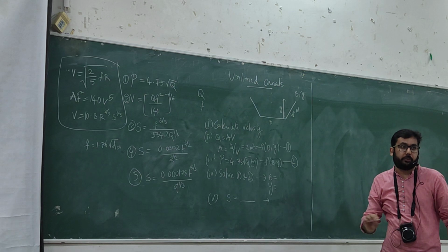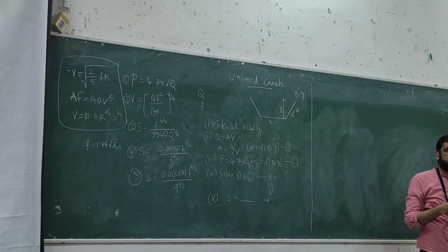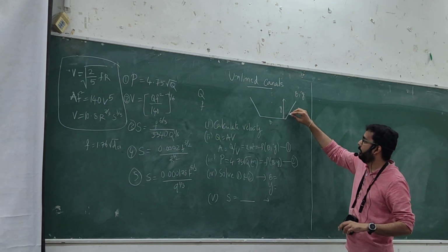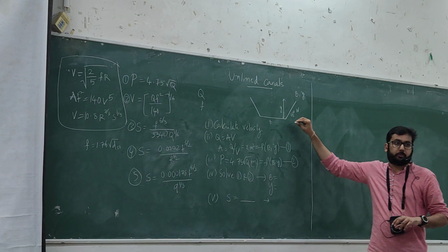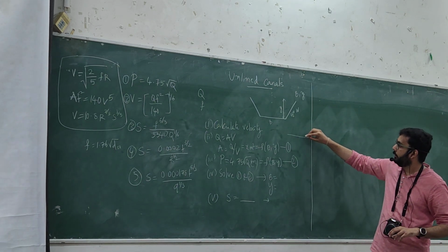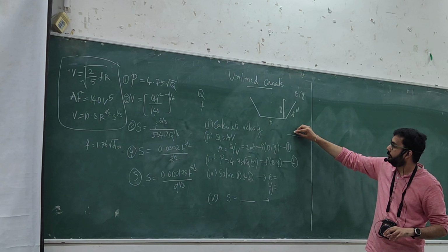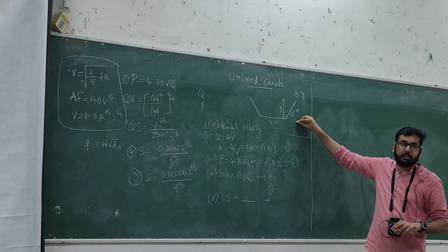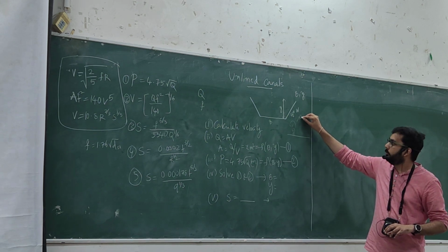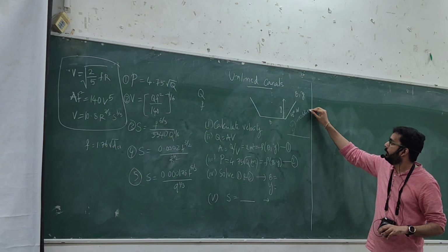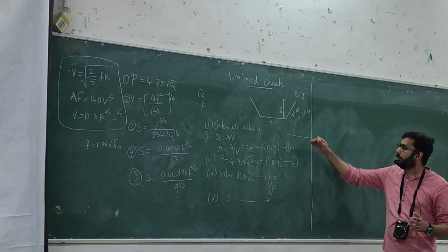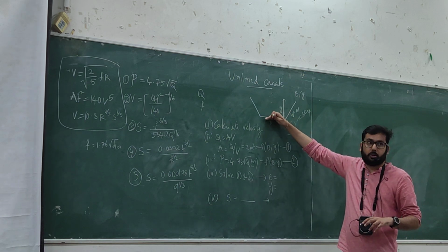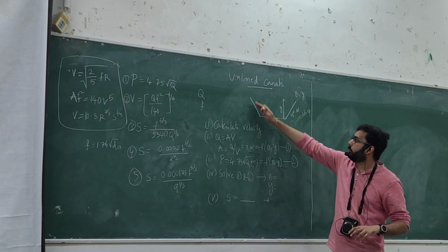And what is the other difference between Lacey and Kennedy that we discussed yesterday? So about something about the bed and the slope. So what are these on the bed? Turbulent eddies. So the other difference between Lacey and Kennedy is, in Kennedy he only considers turbulence or eddies coming from the bed, whereas in Lacey's he considers them from both sides.